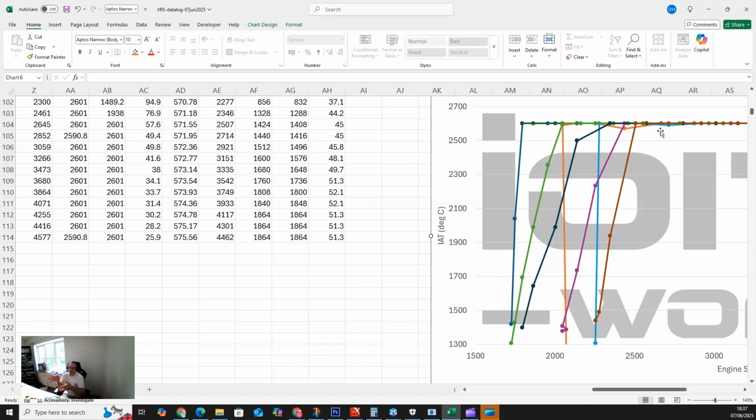Your engine speed is increasing, again in a high load situation. Your mass air volume through the engine starts to increase, and all of a sudden, as the turbocharger comes on, you get a huge boost in volume of air through the engine. Your boost pressure skyrockets, and next thing you're overshooting to the moon, and the system is going, oh no, we've really shot past the moon here, we need to turn around and come back a bit. And then your system is struggling to keep up.